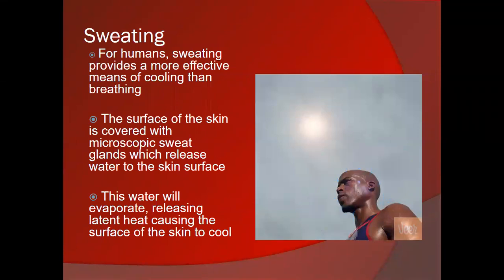So what happens with the humidity is, when it's a very low humidity, like 20% humidity, the water will evaporate very quickly off your skin. It's very easy to cool down. When it's around 50% humidity, it starts to feel a little less comfortable because any sweat that's on your skin is going to evaporate at approximately half as quickly as it would if we're completely dry out. And of course, at 100% humidity, your sweat's not going to do anything to cool you down.